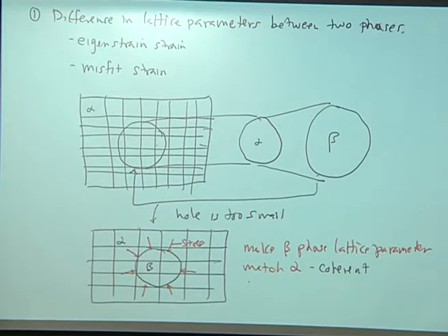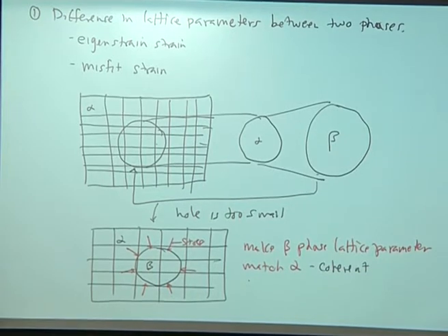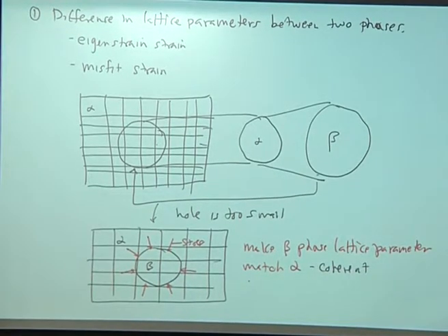And then when you relieve the stresses, I think what's pretty clear is that after you relieve the stresses, the beta phase will push out against the matrix a little bit, and you'll get some change in the diameter of beta as it relaxes. So this is the relaxation once the stresses are removed.